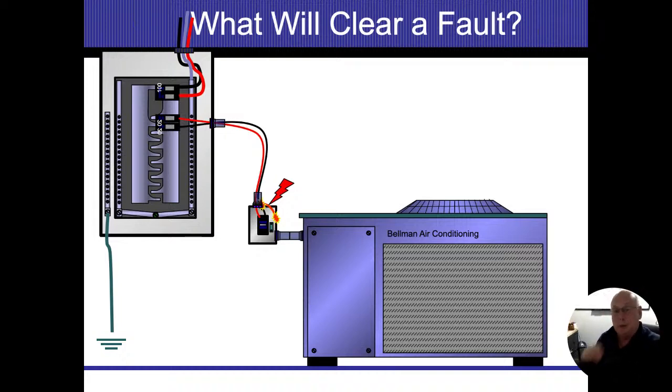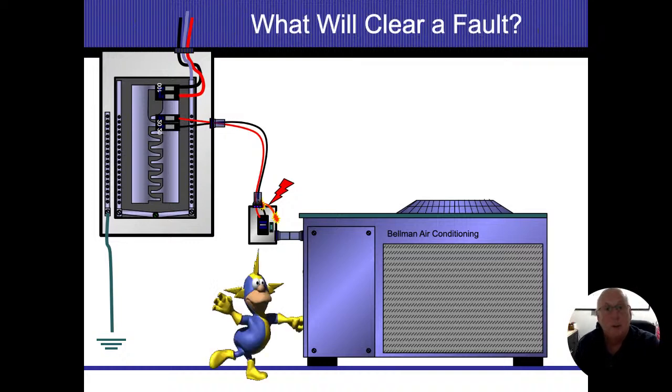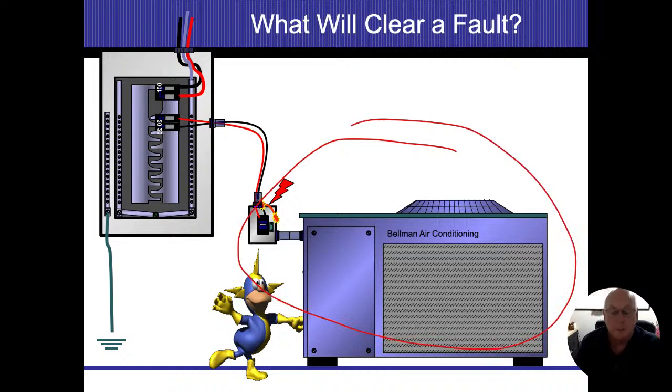In this situation, once that energized conductor comes loose, touches the box, my entire air conditioning system over here ends up energized, all right? So if everything here is energized, then I'm not able to clear that fault.